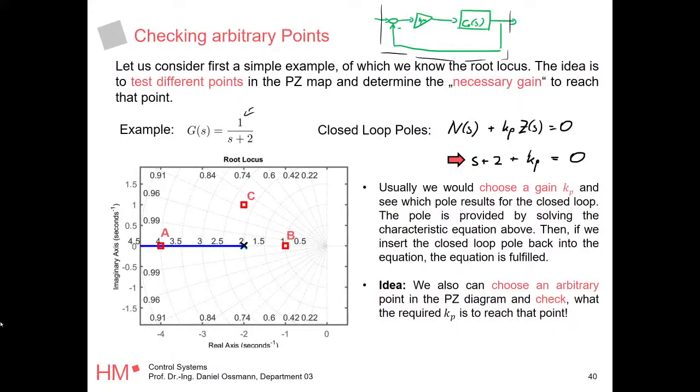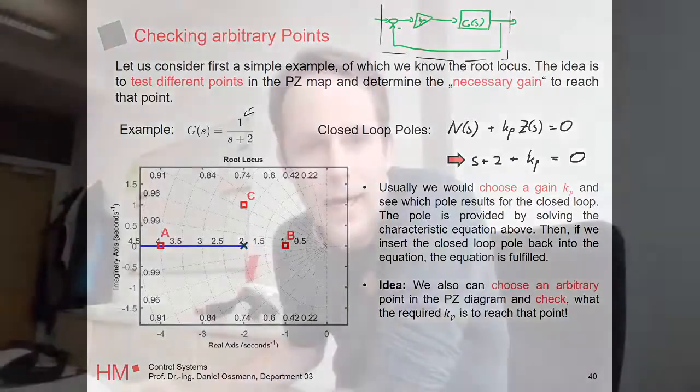And actually we have kind of done this when we did the pole zero cancellation. We basically partly defined the pole by saying we want to have a damping of 0.6. This is also defining a second order pole pair, just one part of it, right? A pole pair has a real part and an imaginary part, or it has a frequency and a damping. This goes hand in hand. So if you define only the damping, you're basically setting one part of the equation.